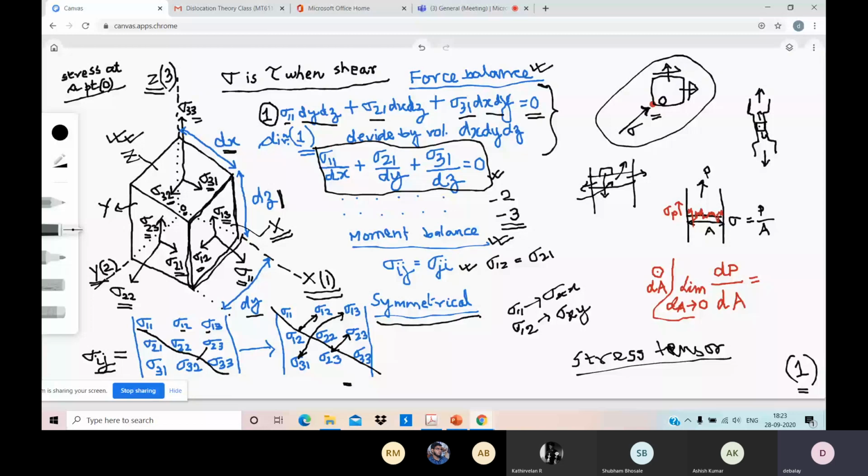So ultimately, how many independent stress tensor components are there? There are 6 stress components, because if you know the 6 components, 3 normal and any 3 shear stress values, you can complete writing the tensor.